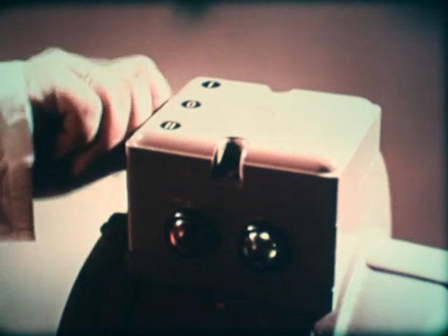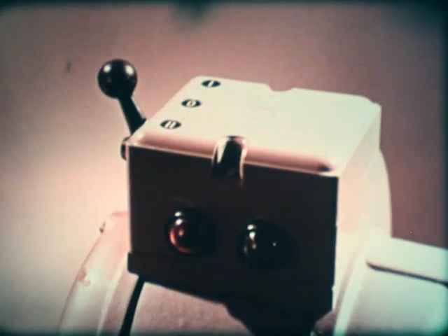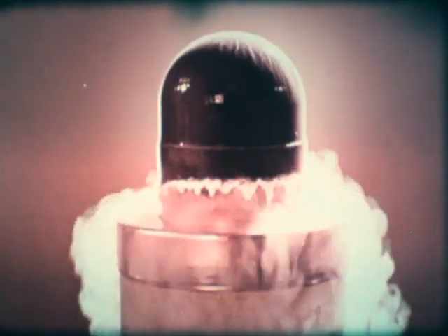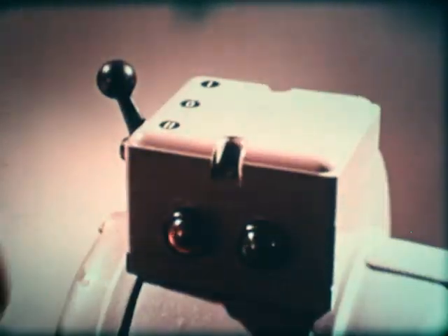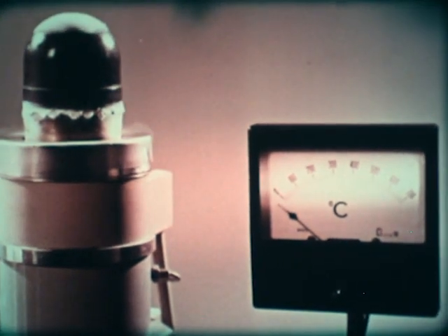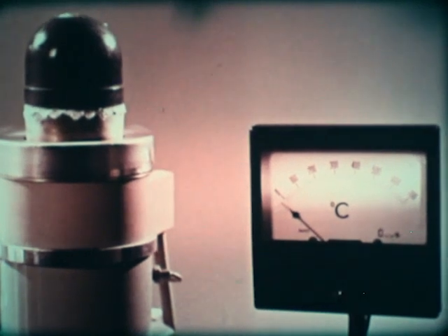When the electric motor is switched off, the machine itself will start to run, but in the reverse direction. It acts now as a cold gas engine as long as the head remains cold enough. Before the cold gas engine comes to a stop, the electric motor is switched on again to keep the machine running in the reverse direction. Therefore, the head will continue to be heated up, and the machine now operates as a heat pump.